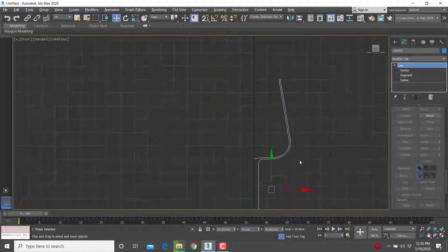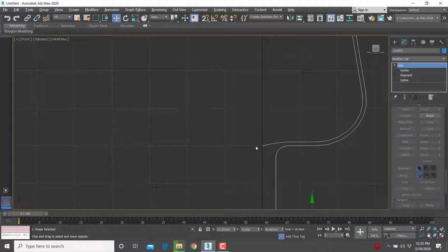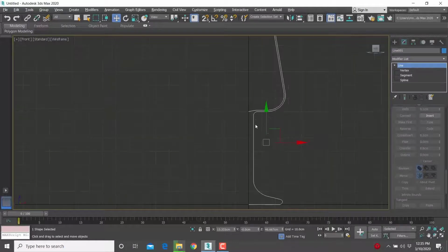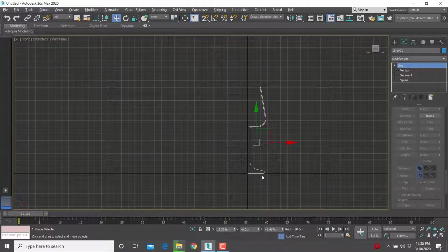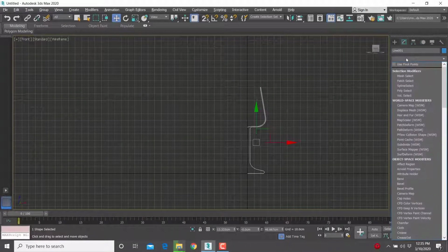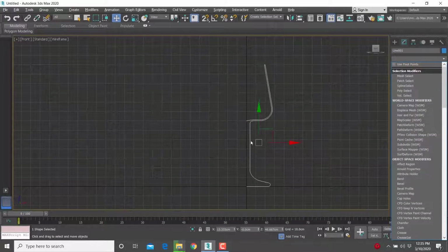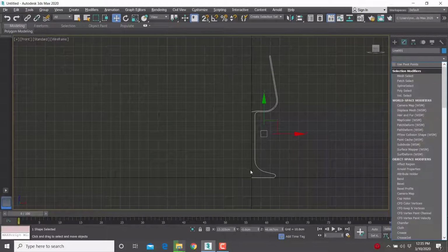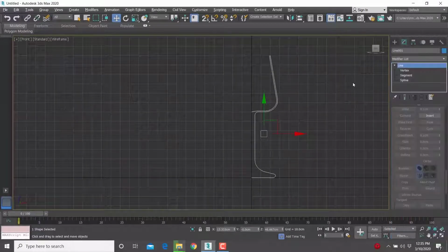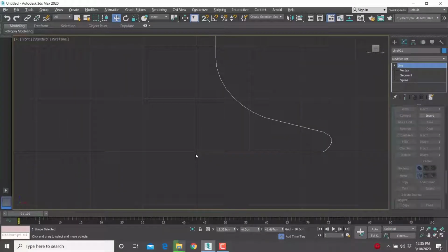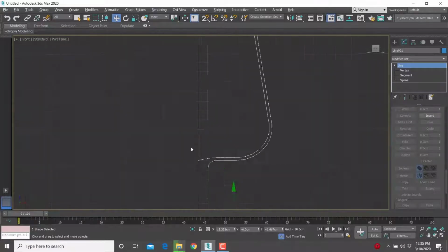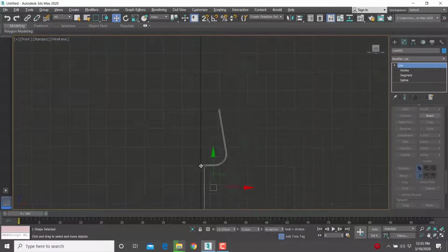Okay, it's gonna come here, and in here it's gonna continue from the other side, and this is the thickness of the handle, and this is the base. So I drew the outline of this glass, and then I'm gonna go to modifier. Just make sure that this point is coherent with this point, so I don't have any holes in the middle. Okay, so I won't have holes. So this is snap to this point, and this is snap to this point. That's why I did snapping.